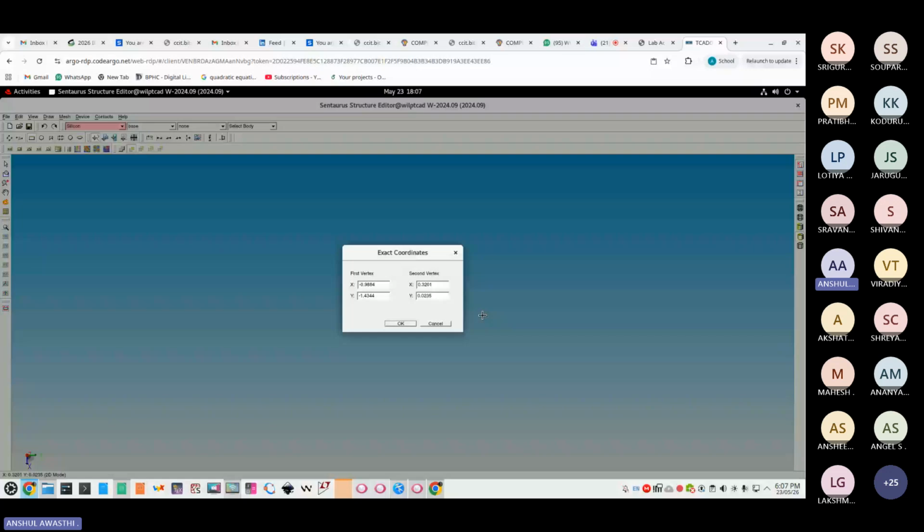So first I'll define my silicon region. There were two silicon regions. First was the N region and second was the P region. So the length of my N region, let us assume that I am starting from 0. So I'll start from 0 and the length of my N region is 250 nanometers.